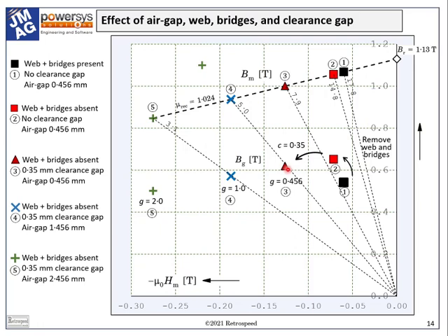The magnet flux density falls from 1.057 to 1.001 Tesla, about the same percentage drop. And that's consistent with the theory of the equivalent magnet, which we mentioned earlier, and which is described on page 165 in the Green Book and elsewhere in the public domain literature.